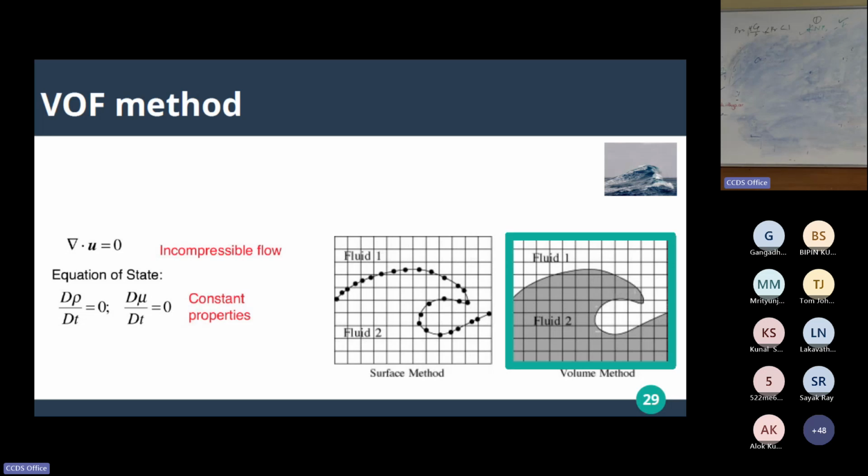So something like fill liquid everywhere, volume of fluid, the entire volume you will focus on, gray color, white color, some part is gray color, some part is white color. So I always sense how quickly that alpha field or color variation is happening in that mesh. Based on that variation, I will be in a position to apply the force and redistribute it.